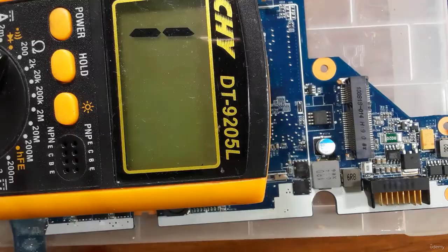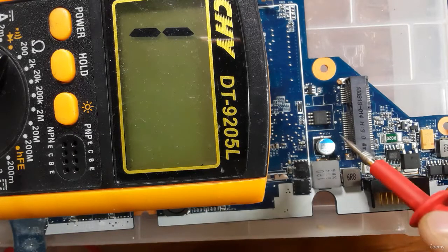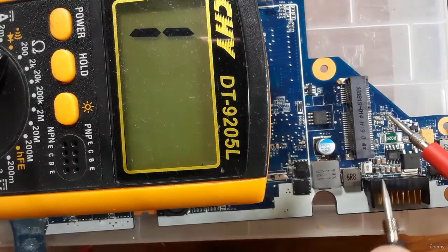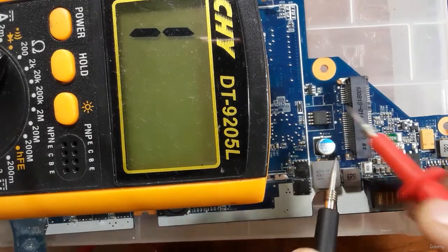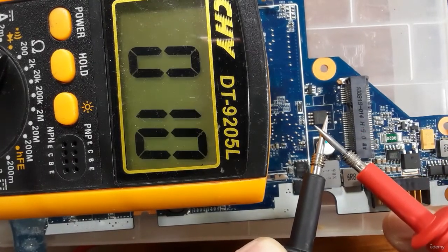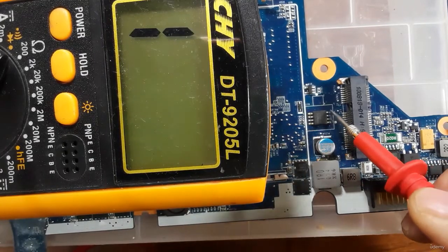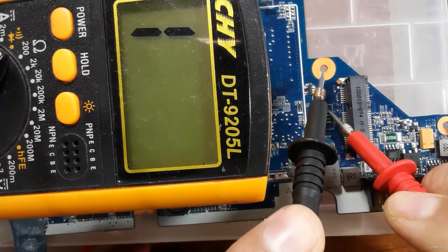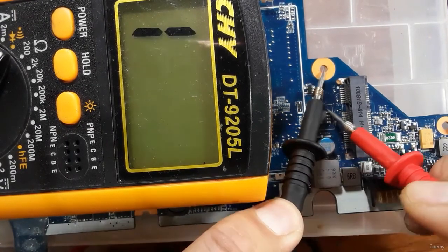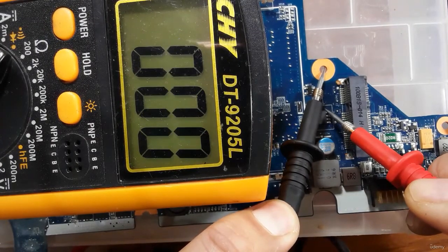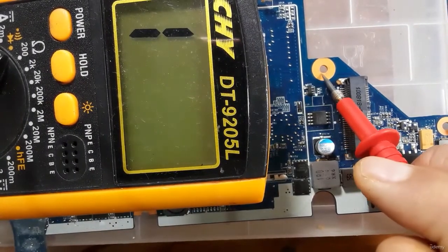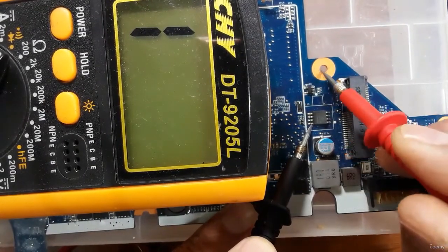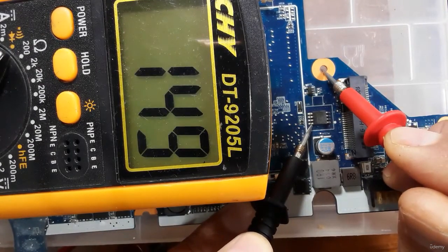Okay, so as I told you, we have pin number 1, 2, 3, and pin number 4 is always connected to the ground. So let's check pin number 4. Let's first check the continuity. The continuity is set correctly. I will put the red probe on pin number 4 and the other probe on the ground. As you can see on the multimeter, low resistance means pin number 4 is connected to the ground. Pin number 8 should not be connected to the ground because pin number 8 is connected to the power rail. It's not connected to the ground.